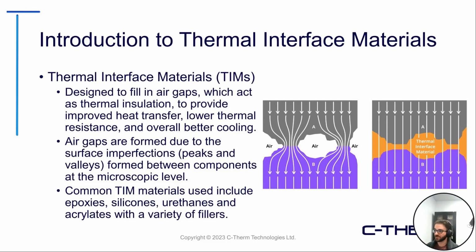Now, those air gaps are really due to very tiny surface imperfections formed between those components at the microscopic level. So if you zoom in on what may look to be two flat surfaces, in reality, there are all these little chasms and void spaces present there. So again, these TIM materials are brought into play to help bridge that gap.